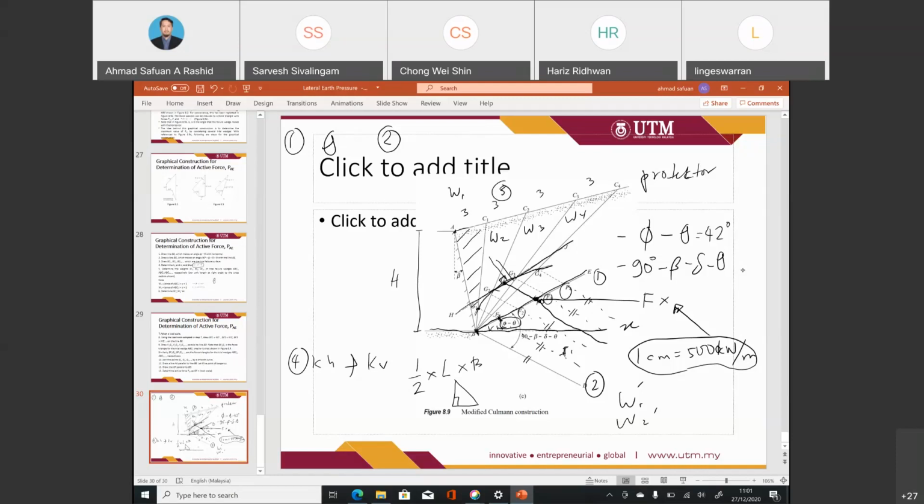The third step, you may construct a trial failure surface on the top of the slope, for example here, with approximately the same interval of distance. For example, A to C1, 3 meter. C1 to C2, 3 meter. C2 to C3, 3 meter. C3 to C4, 3 meter. So that is step number 3 in terms of constructing a line.